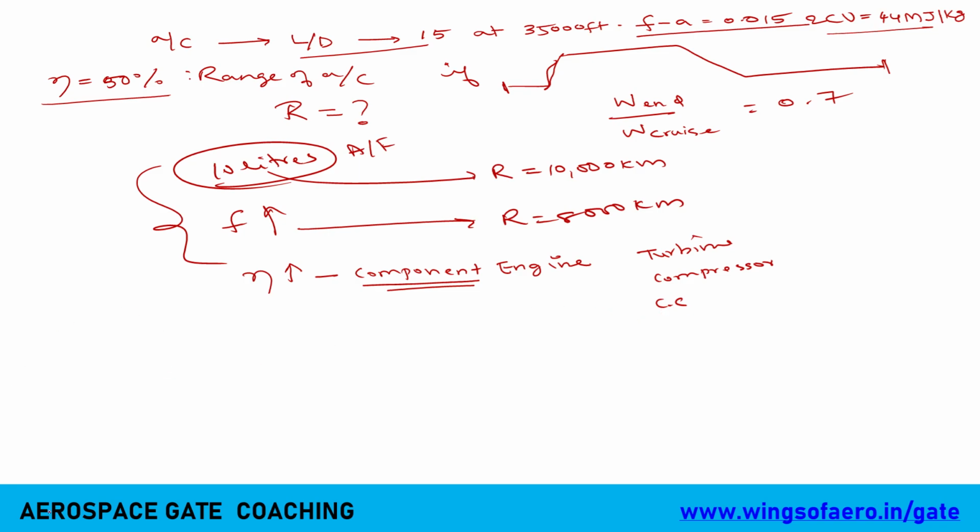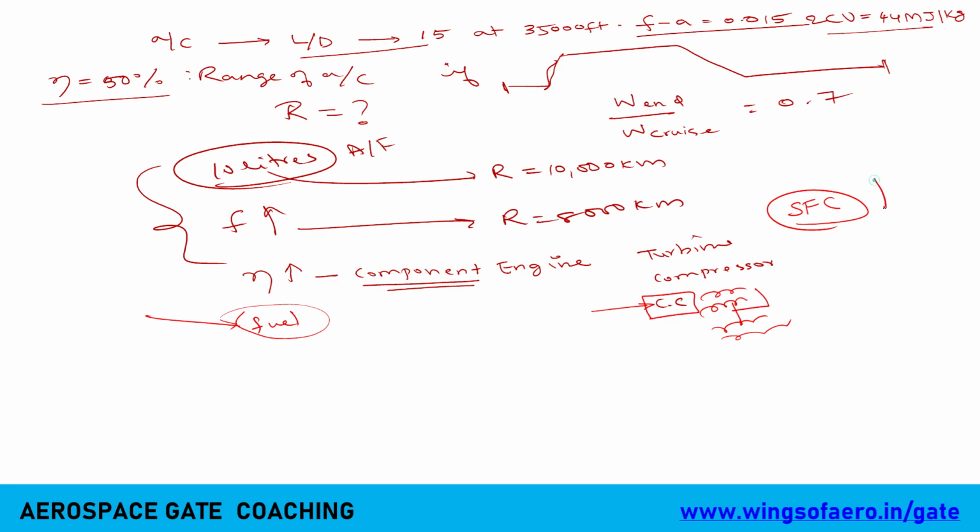Very good. See, this is a very simple question, isn't it? When I said a few simple things, you got confused, and this is what GATE exam question papers look like. The questions are hidden behind it. From where do we inject the fuel? Because of fuel efficiency, we have to give more focus to the combustion chamber only. We have to take care of the combustion chamber. Maybe we have to implement baffles, so better turbulence takes place and we can get complete combustion. Incomplete combustion increases the SFC, or the fuel burn, because of the problem in the combustion chamber.